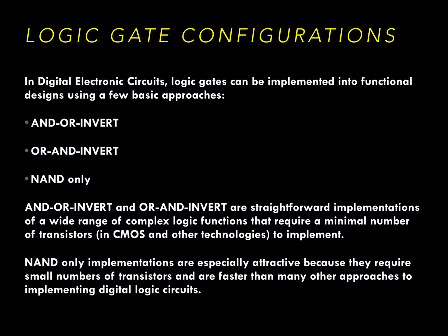NAND-only implementations, while they require some Boolean manipulation to come up with, are especially attractive because not only do they consume a small number of transistors, they are also faster than many other approaches to implementing digital logic circuits. Today we'll look at all three configurations.